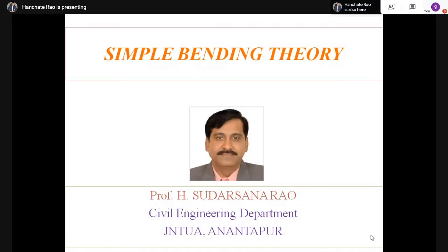So there is no point. You can follow any sign convention you want, whether this sign convention or, in the case of bending moment, I proposed sagging bending moment as positive and hogging bending moment as negative. I also said certain textbooks use sagging as negative and hogging as positive. So there is nothing wrong. We can use any sign convention, but my only request is don't mix up the two sign conventions.